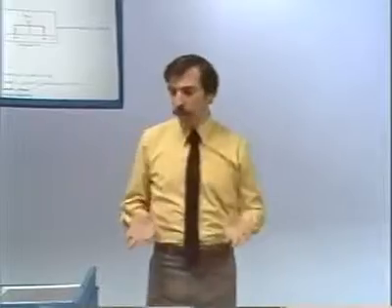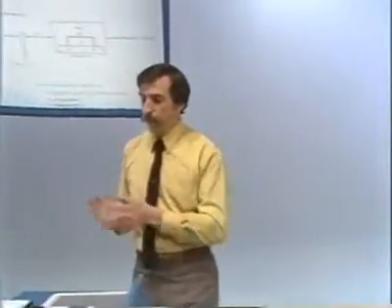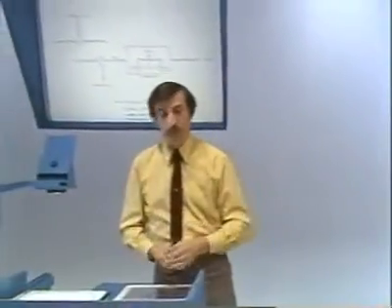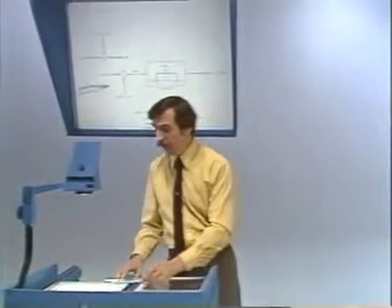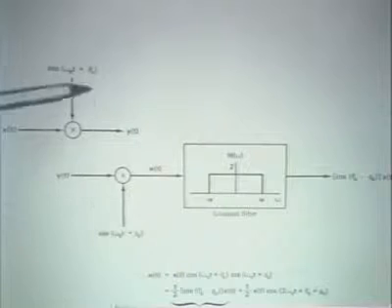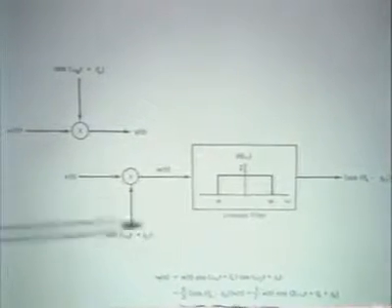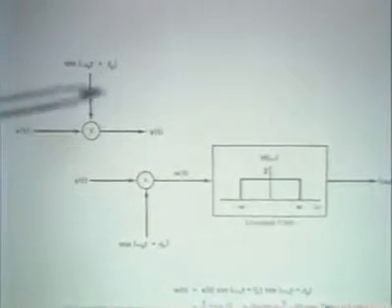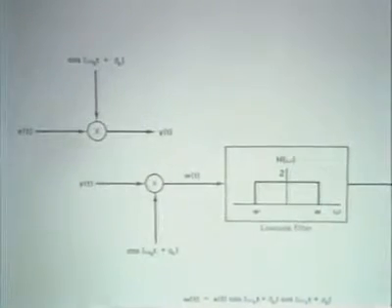What that means is that if you use this kind of system to do the demodulation, you need to be careful about maintaining synchronization in phase, and also, as it turns out, in frequency between the modulator and the demodulator.